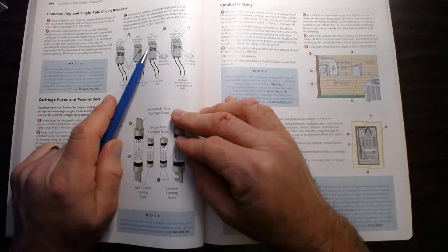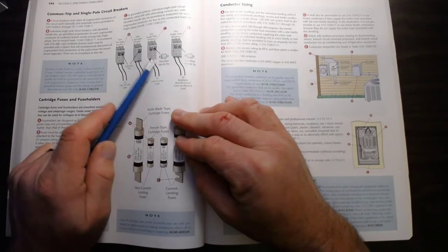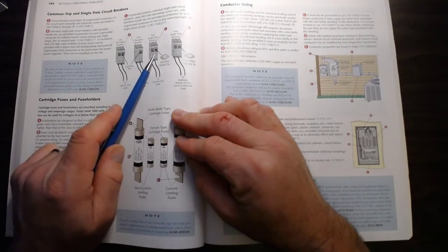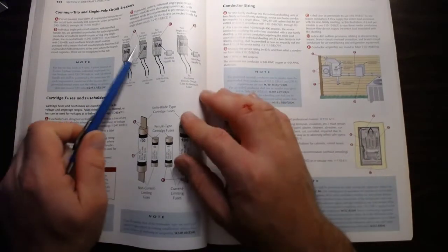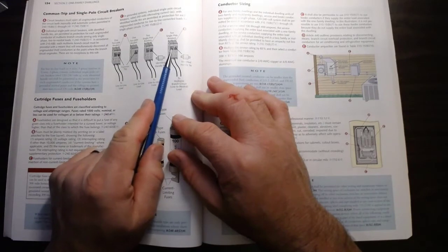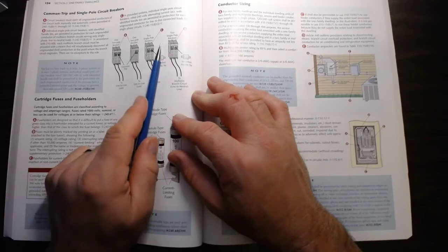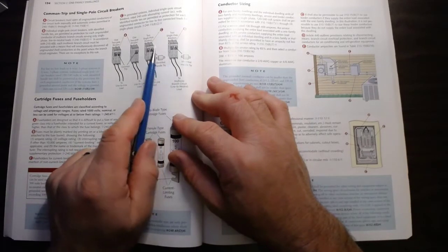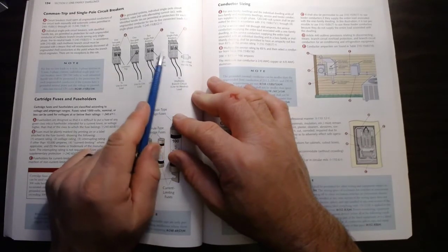They used to have circuit breakers that were stackables and you could put them together and then add these devices in. They've gone away from that. It's hard to find those anymore. And the newer ones are all factory made to be common throws. There may be a situation where you have a 2-pole or a 3-pole equipment, and you have a single pole control power that you want to trip at the same time. And so you might have a breaker that has up to four connected on the pole there.